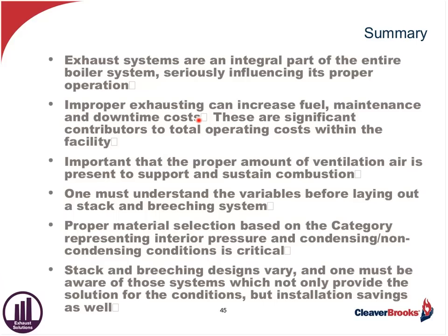So keep these things in mind when a boiler is added or when new boilers are being installed, or another one is being replaced, like I mentioned before, an old coal-fired plant being replaced with gas or oil-fired boilers. The venting of these new boilers becomes very important, especially if the existing stack or chimney is being used. Ventilation air is also very important. Let me just give you an example.